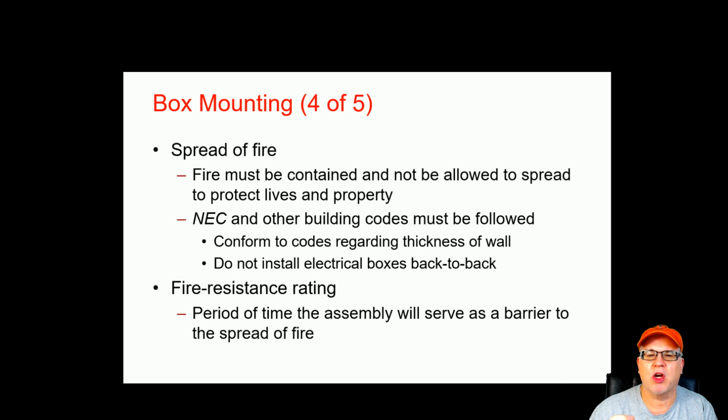Conform to codes regarding the thickness of a wall, what types of gypsum board I have to install. Maybe it's a type X in the ceiling of a garage, and you've got to be very careful what I put in there, because we don't want to lose the integrity of that barrier. Do not install electrical boxes back to back. And I'll show you. This has to do with if I've got a rated wall and I have to maintain a separation in that rated wall.